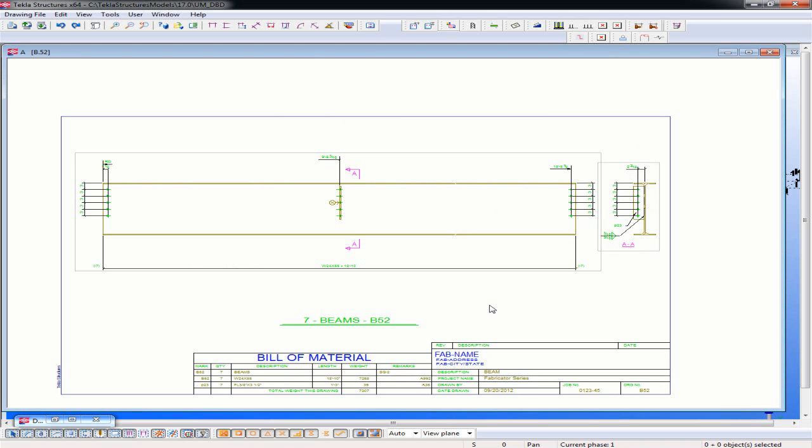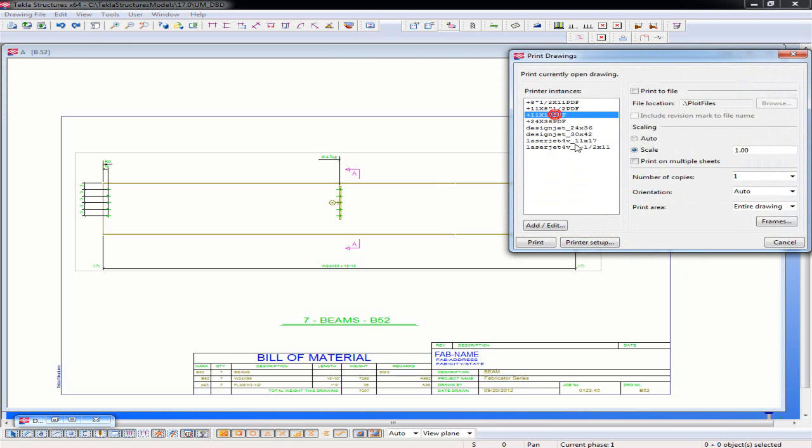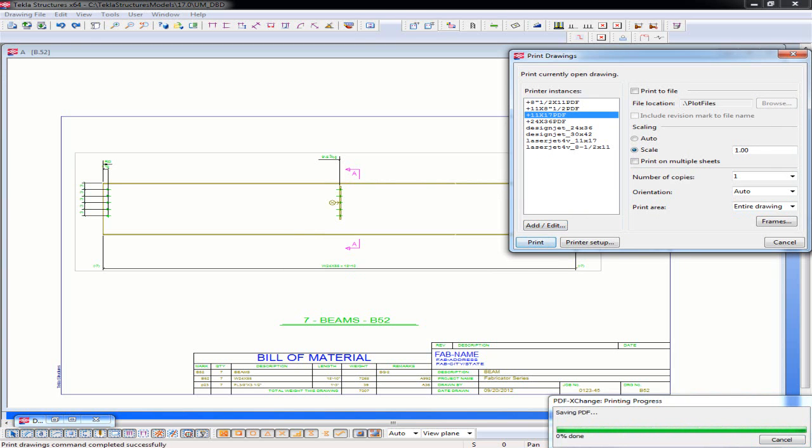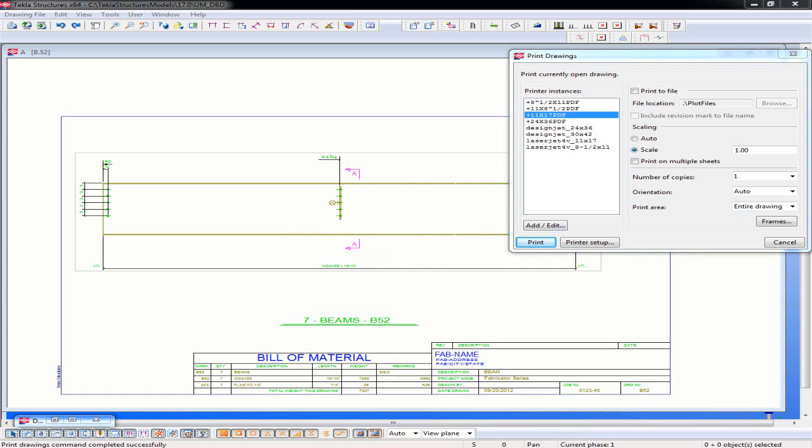So within the viewer license, it is read only. You don't have the option to save the model or to save the drawings. But there's a couple of options that you have here, which is that you can actually come in and print this drawing. So if you wanted to just print this and make a PDF of it, I'll just go ahead and select my printer, the size, visible area, or entire drawing. Just click on print, and then we'll go through and PDF that guy for me.